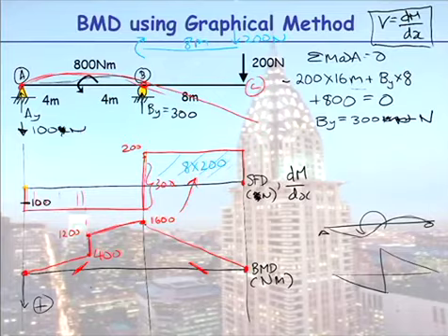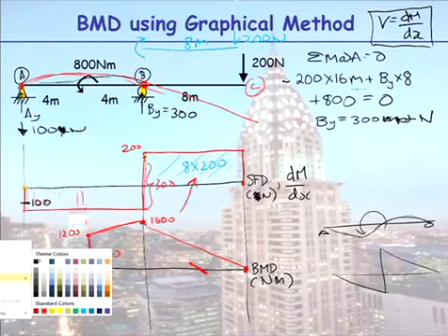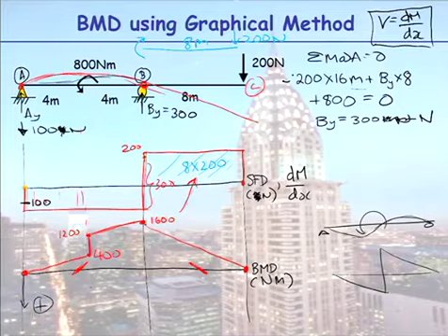We finished up having completed the bending moment diagram where we had a simply supported beam with a point load and a moment. The bending moment, when we drew it, was all above the line. Because we draw our bending moment on the side of the beam in tension, from that we could then say what our deflected shape looked like, and we drew our deflected shape as having tension on the top throughout, because our bending moment told us that.